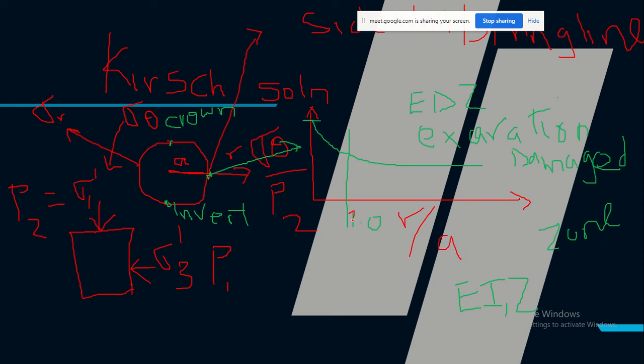This is two. So the physical meaning is that in this area there is high stress readjustment due to the unloading, and therefore, for all intents and purposes, this can be called the excavation damage zone, when R over A is 2.